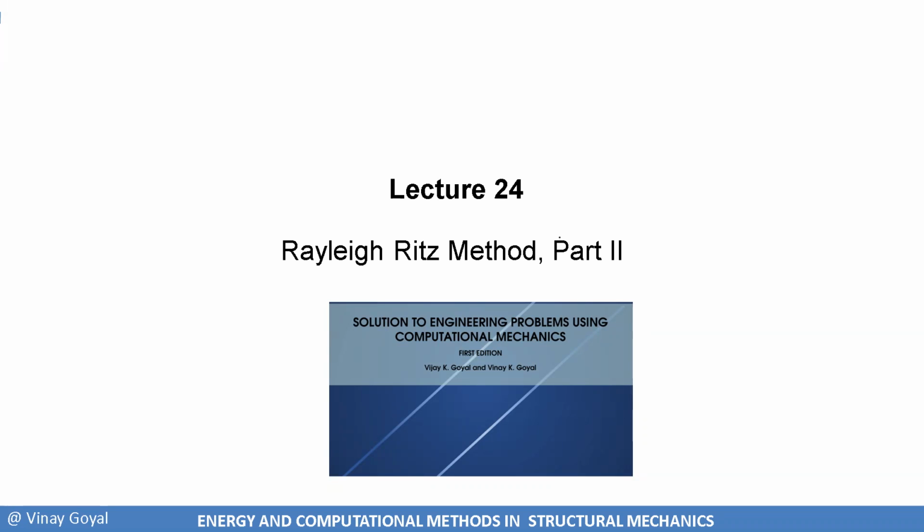And from there, I then derived a number of equations using structural mechanics. I started with deriving the governing equations of elasticity. I could have chosen a different area of expertise, like heat transfer or fluid mechanics, but I chose structural mechanics. I then derived the equations using the integral form of Newton's law and came up with the 15 equations and 15 unknowns that comprise the equations of elasticity. Those are the strain deflection relationships, the stress equilibrium equations, and the stress strain constitutive law.